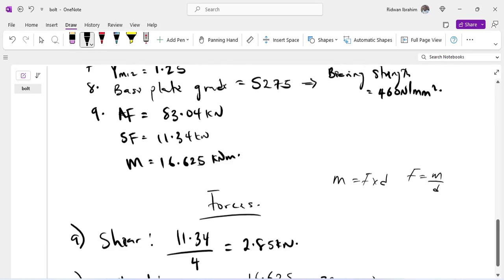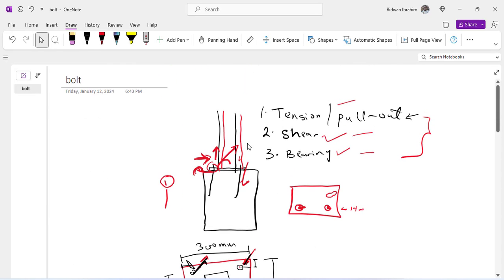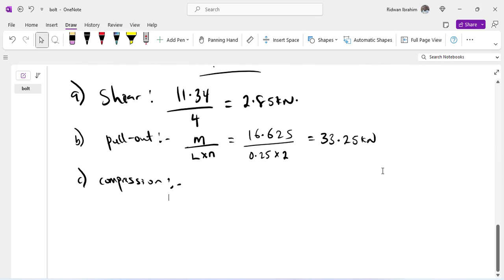So what I'm trying to point out is that when you have a vertical pole like this, and then we have our bolt inside, the axial force will be pushing this bolt inside. If the axial force coming from this UC column is pushing our bolt downward, causing compression on our bolt, that means I can subtract that compression force from this tensile force that we have calculated.